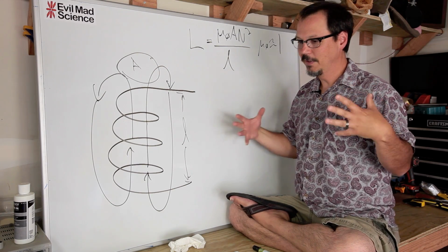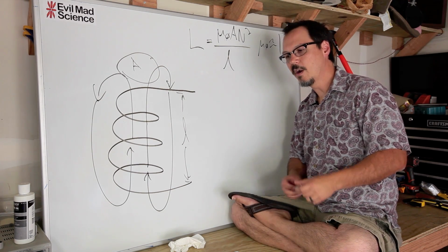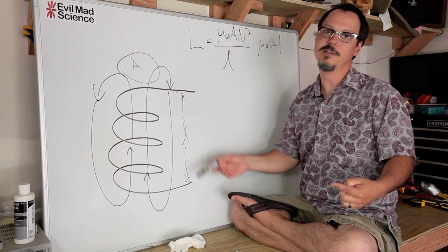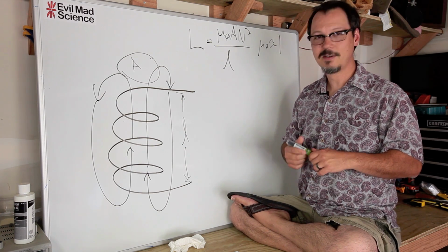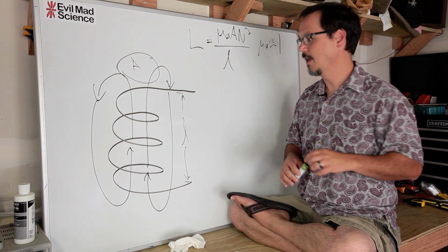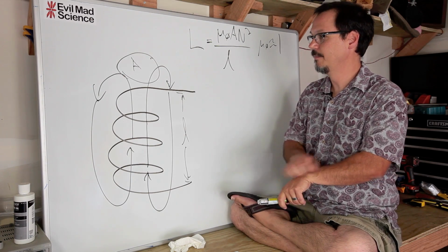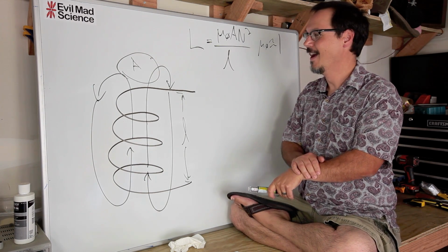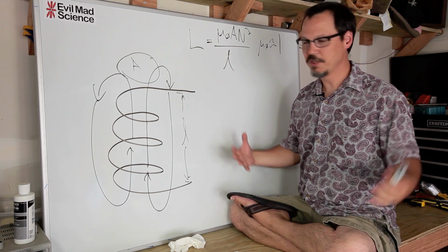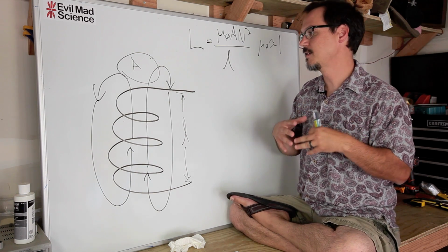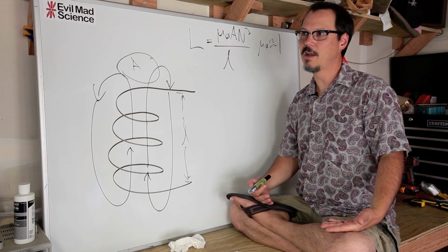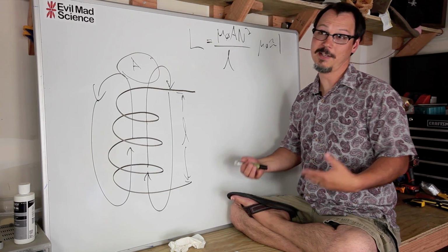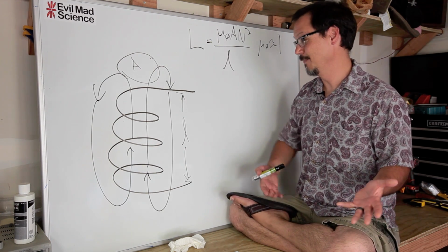That magnetic field will a lot of times cut across your other circuitry and induce a bunch of junk that you don't want in there. That is called flux leakage. So for that reason, they design inductors specifically to maintain the flux. Maintaining the flux makes the device a lot more efficient. It makes it quieter, which you need it to be.